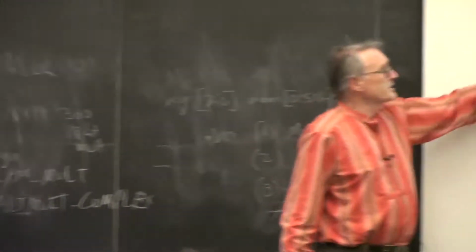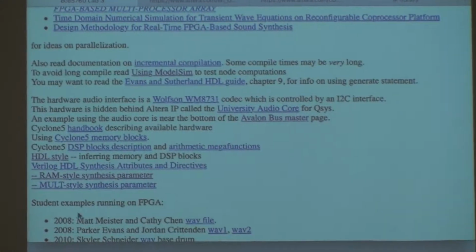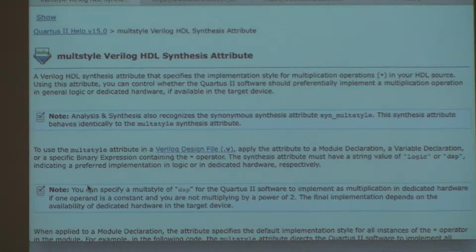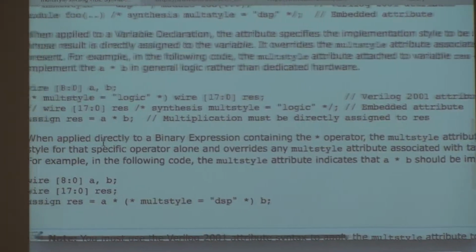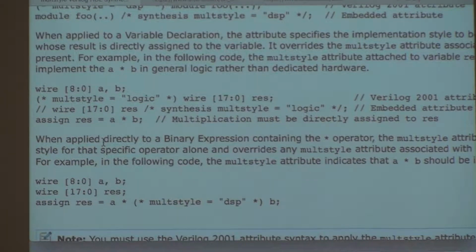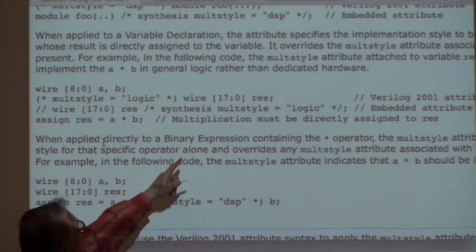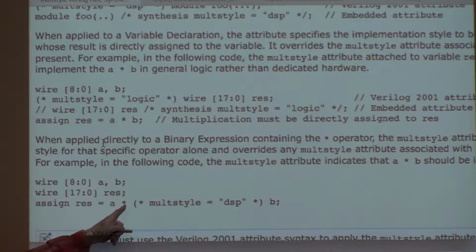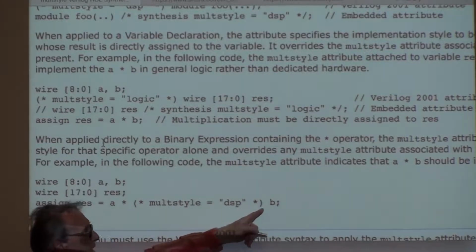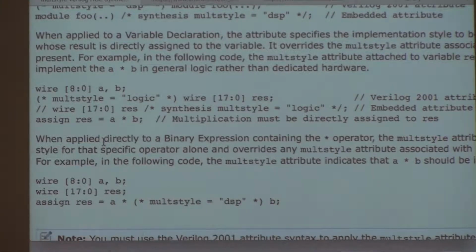There's the mult style synthesis parameter, which has an even odder syntax in that you specify the output wire to be a mult style logic, or you do this crazy thing, times mult style equals DSP B. So you inline the style with the operator.